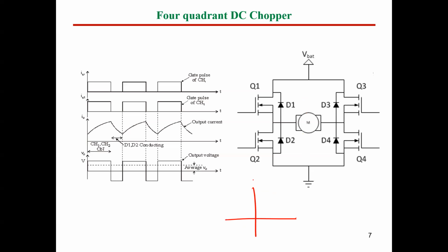For speed and torque, you can have different modes of operation, which means it can work in forward mode here. So this is called motor. It can work as a reverse motor, and reverse motor means you are going to reverse the torque direction, okay? So the energy is going to be reversed, and in this case, it's operating in reverse power mode as a generator, okay?